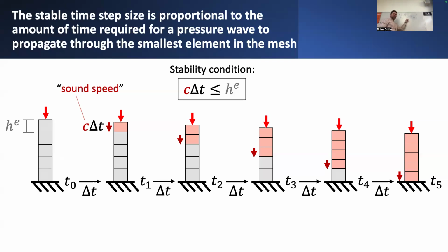Now, depending on the properties of this matrix, which is going to depend on a bunch of different properties, like what's the mass, what's the stiffness, and what's the time step of the problem you're looking at for a given time step between tn and tn plus 1, this matrix will have a particular eigenvalue decomposition,